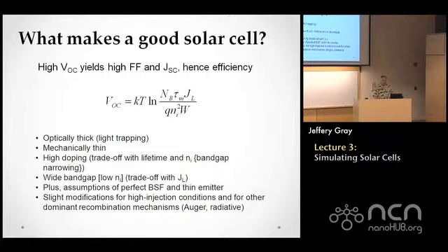But you typically would, and the bases of typical silicon solar cells are 10 to the 16th, 10 to the 17th. And the reason they do that is to get a pretty high open circuit voltage. There's also another regime which is actually very lowly doped, and that's where you get into high-level injection. But again, you would have to derive for that particular condition.